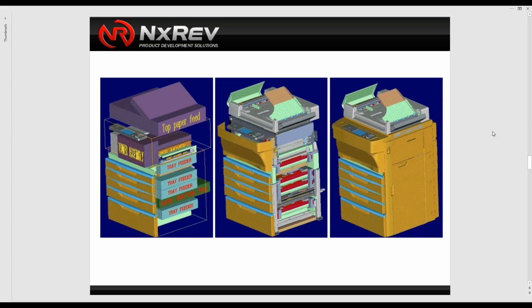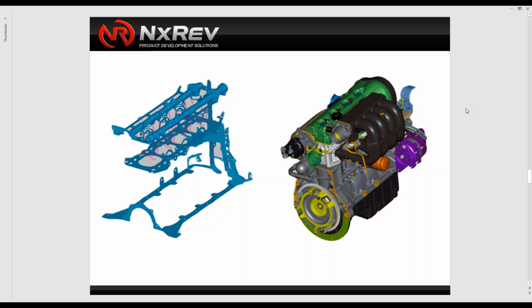Another example of a skeleton is a skeleton that contains critical interfaces. So here we have an engine assembly, and here we have actually surfaces in this skeleton to define interfaces between the components within this engine assembly. Okay. Any change to the interfaces of the skeleton can update the corresponding components. All of these are surfaces that are basically shared common areas between components of the assembly.